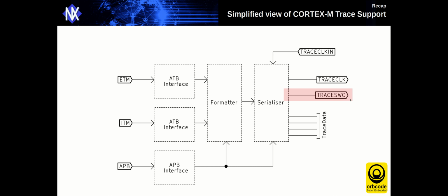and the data that comes out of here can be formatted in two ways, in a Manchester encoded stream, or rather more conveniently as UART encoded frames. What this means is that you can just plug a TTL UART onto port B3 and you get trace SWO out at some bit rate or other, which is reasonably programmable. Unfortunately, that stuff is encoded, and so the job of Orbtools is to decode all of that data and turn it into useful information for presentation to the programmer.